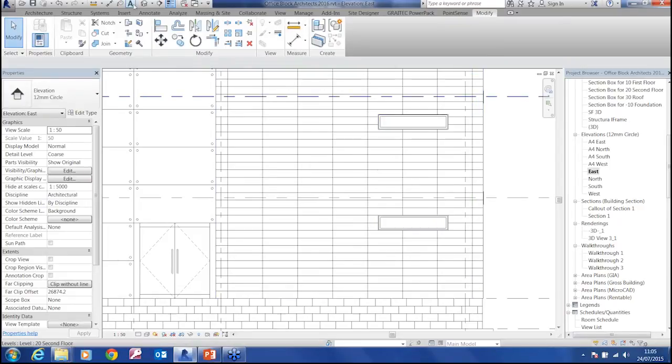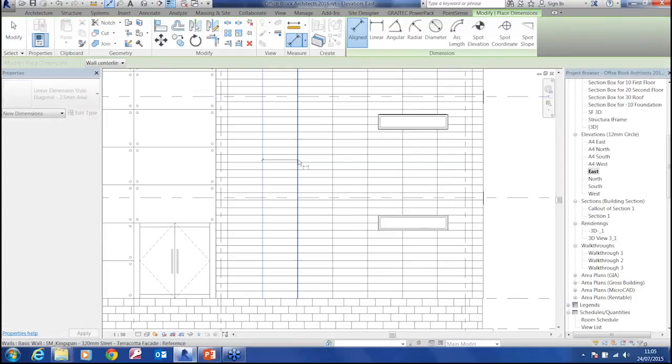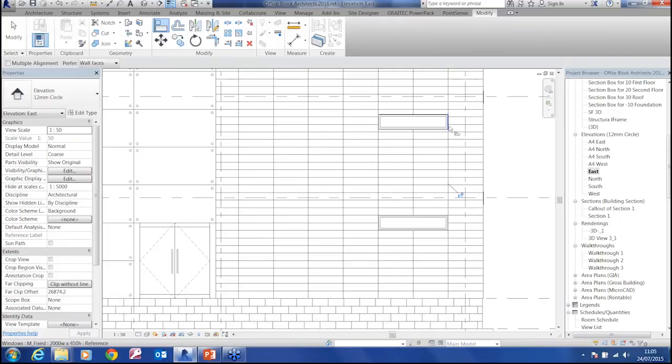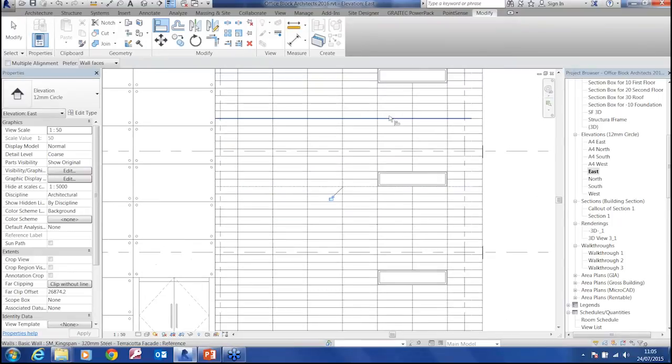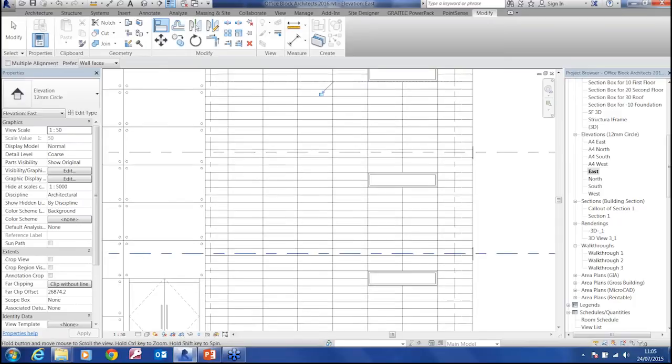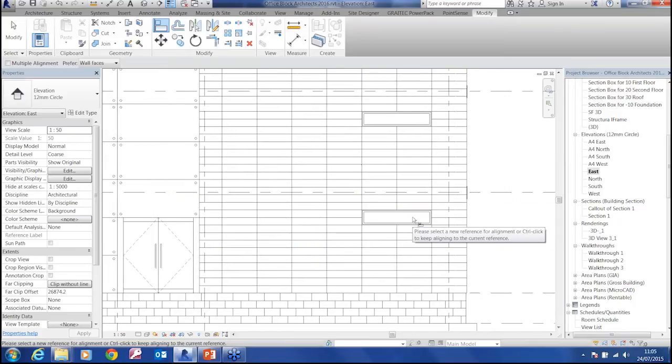This panel is actually a hatch pattern, but it's a model hatch. And if I actually dimension it, you can see it's actually a meter wide. Because it's a model hatch, it does then allow me to have it as a scalable item. I can actually also align the hatch pattern to the windows. I can then also align the window to the hatch pattern, so that we can actually start to place our windows in there perfectly in our panel widths. Okay.